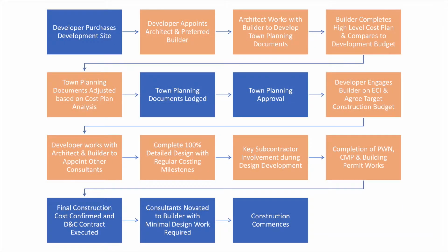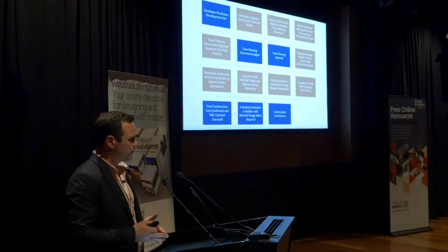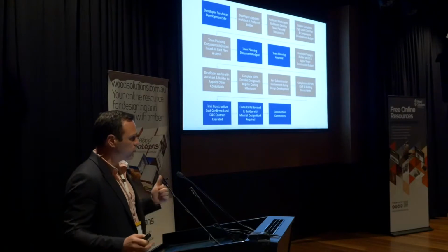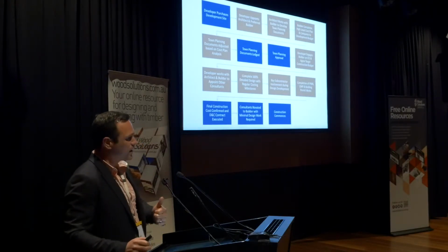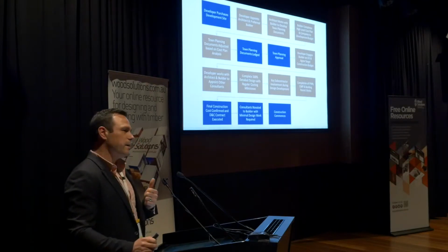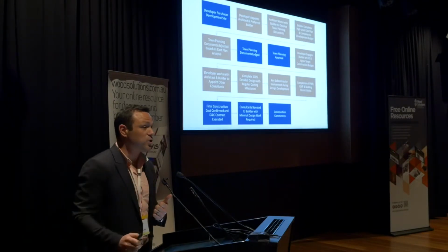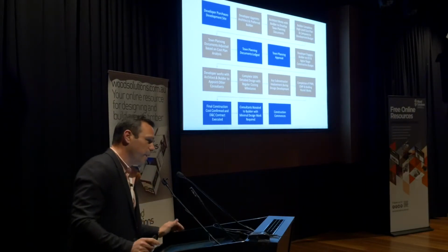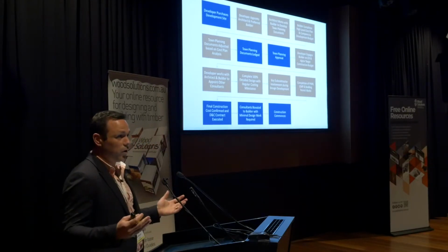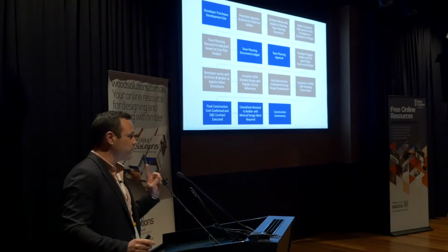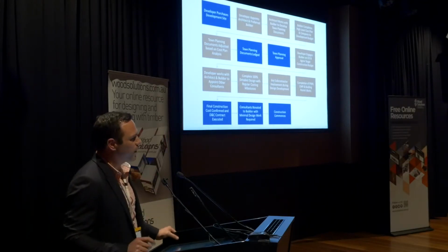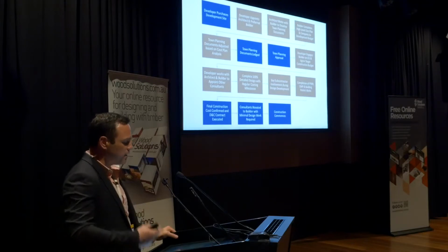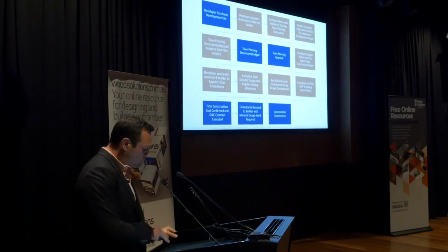And the other key component here is actually completion of, I haven't mentioned this yet, but protection work notices, construction management plans, building permits. A lot of this stuff can't happen until you've appointed a builder, and they take a lot of time. Certain jobs, protection work notices, you can't really hang your crane over an adjacent property anymore. Anyone with any sense can delay you starting a construction site because you'd put in an anchor underneath their property and they're a lawyer, and it just drags on and on and on, and it costs a lot of money and you lose all this time. And the clock's ticking because you've been appointed and you're paying prelims, and it's a really bad way to start a job.